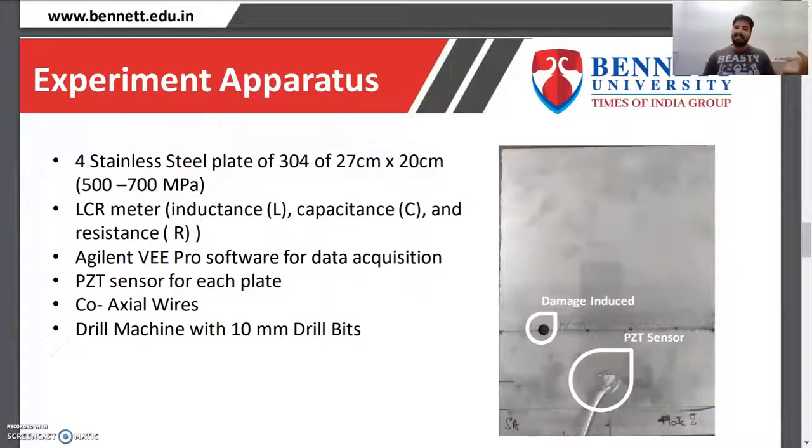LCR meter, that is inductance, capacitance, and resistance, that is LCR. The software that we are using is to acquire data from the LCR meter, taking it into Excel form that we can use for further analysis. The sensor that is taking all the data is the PZT sensor or the piezo sensor, one sensor per plate. And coaxial wire to attach, and then a drill machine to induce damage.